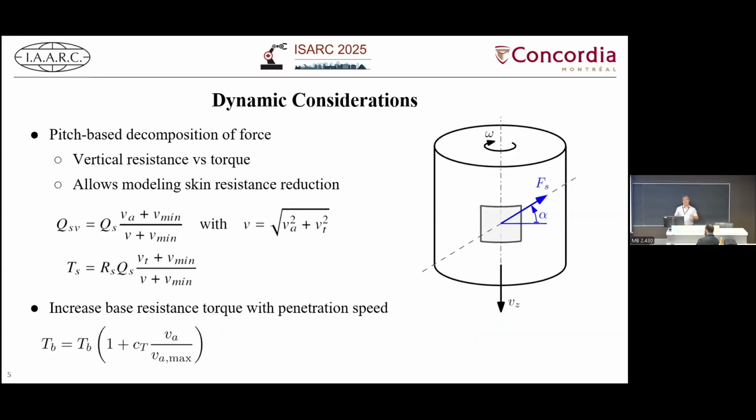But what I was talking about so far are quasi-static models in our case. So we had to augment this with some dynamic considerations. One of these important elements was communicated to us by our client: we need to capture the fact that when the displacement drill is inserting the pile into the ground, it's being rotated to transfer some load from the pull-down resistance of the pile into the rotary motion.